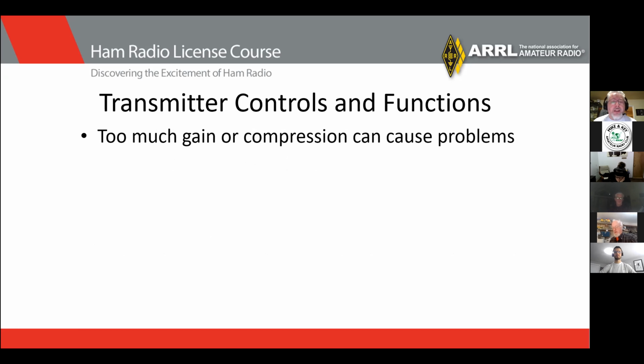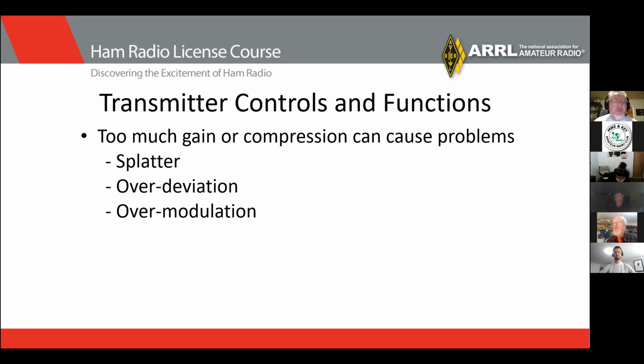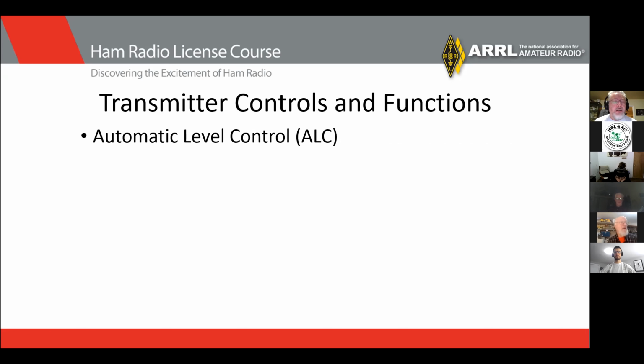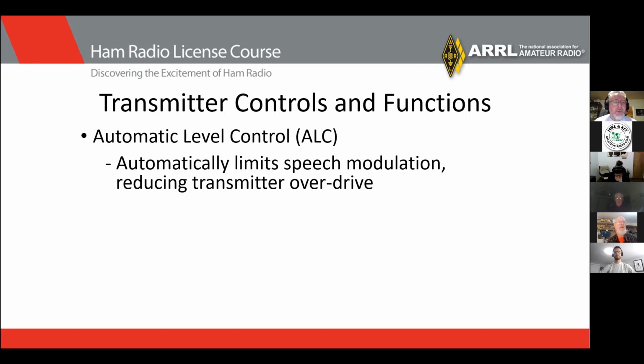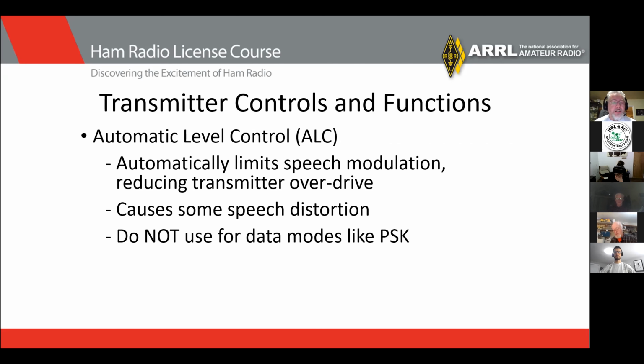Too much gain or compression, though, can cause problems such as splatter, over deviation, over modulation, and so we have automatic level controls or ALC, which automatically limits speech modulation, reducing transmitter overdrive, but it can cause some speech distortion.